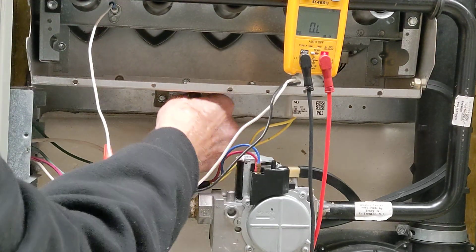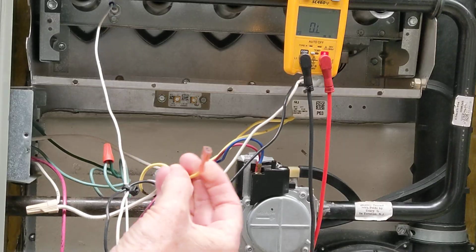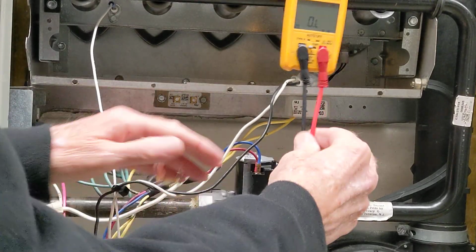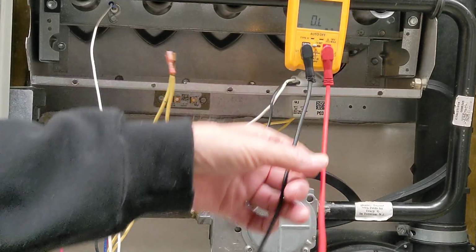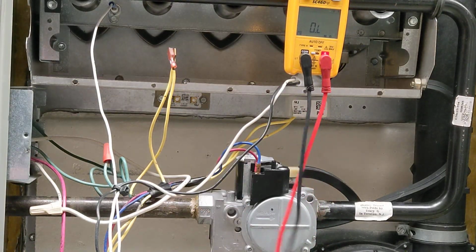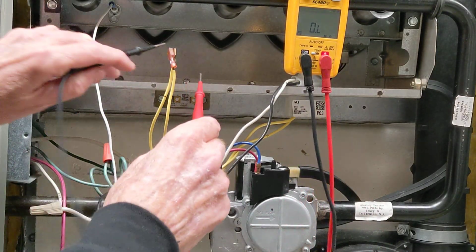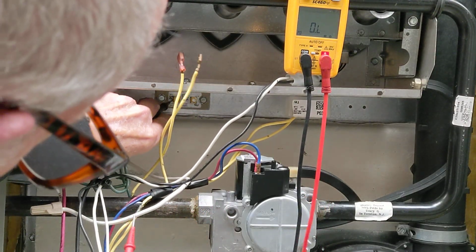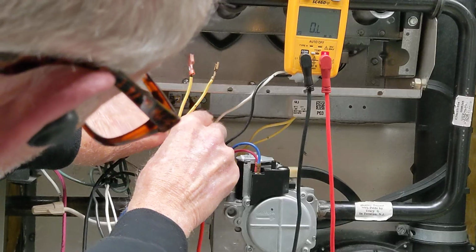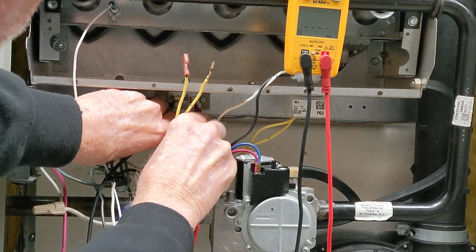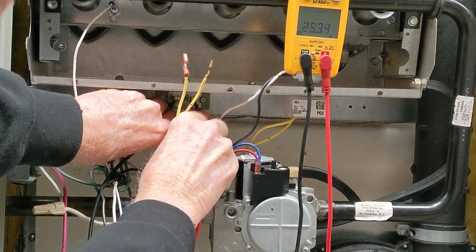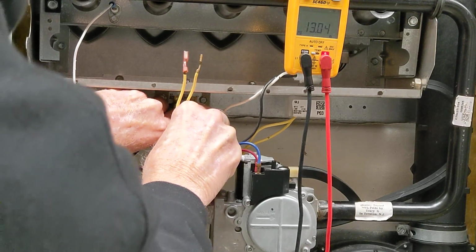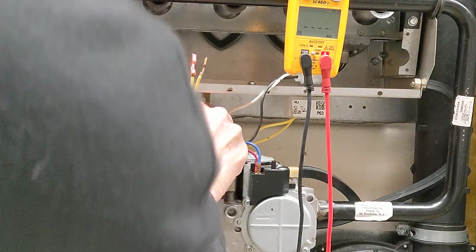I'm going to pull at least one wire. I like to pull them both. I got the power off, so I don't have to worry about this wire touching the metal or anything. Then I'm simply going to come here and measure across the switch. So from one side of the switch to the other side of the switch, hold the lead steady and firm. The meter settles down. And it says about 5 ohms.